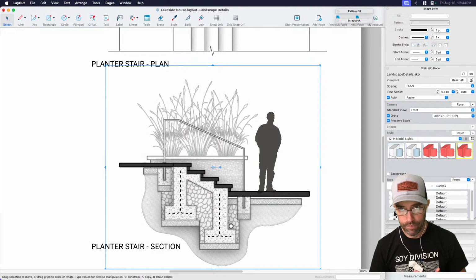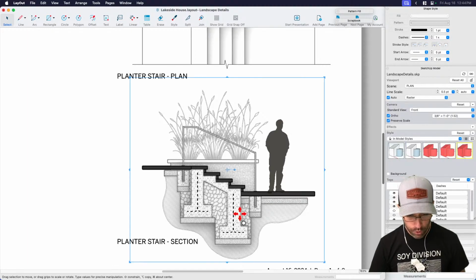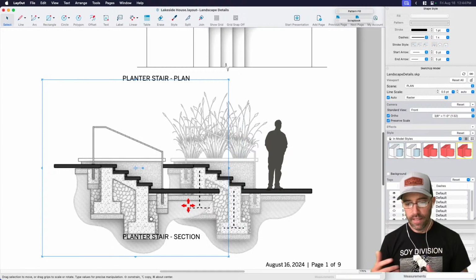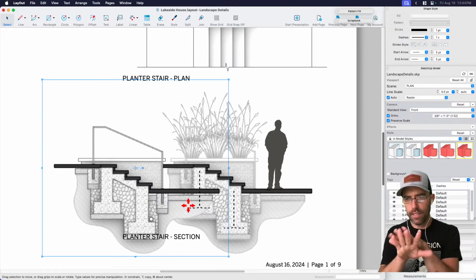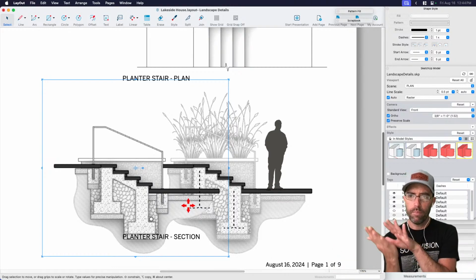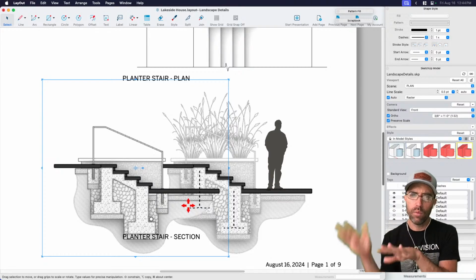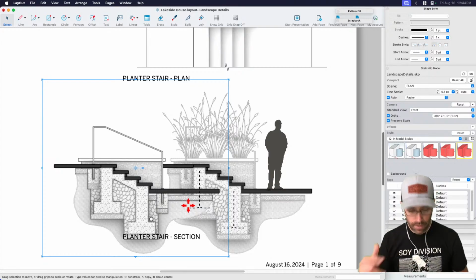Ah, okay, very nice. It's a little visual trick, and it seems like maybe that's not worth the amount of time it took me to do that. But imagine doing this again. You only have to set these styles up once, because then you can apply them anywhere. What I did is a stacked viewport: one with a background using faded line work, and one with a foreground using non-faded line work.